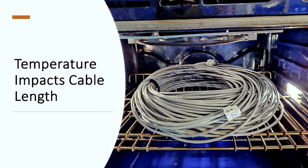Temperature impacts cable length. So this is 295 feet of Cat6 that I stuck in my oven. Now, my wife heard me beeping away on the oven, and she said, "What are you cooking?" Because she knows I don't cook. And I said, "Cat6." And she said, "Okay." Because she's used to me doing things like that. Now, the one rule is I can't stink up the house. Can't heat it up that much. But what I did was I heated this up to 135 degrees, because that's about where I could get it and it wasn't starting to smell.